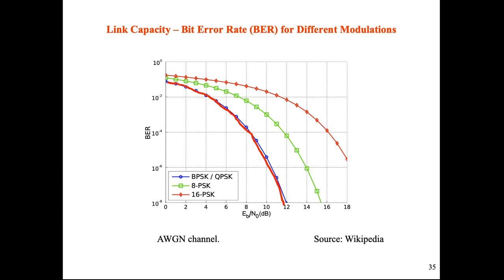And we said that in order to have a bit error rate between 10 to the minus 6 and 10 to the minus 5, we have to maintain an energy per bit roughly in this interval around 10 dB. So this is the ratio, from 9 to 10 point something dB.